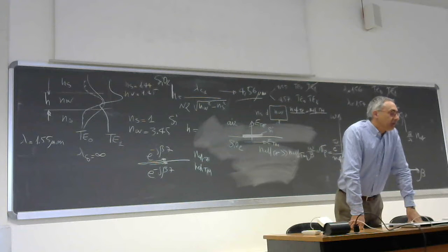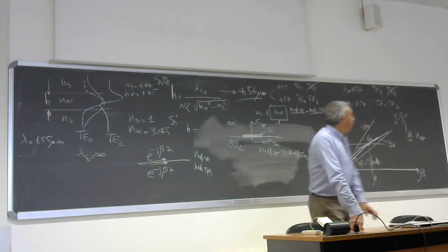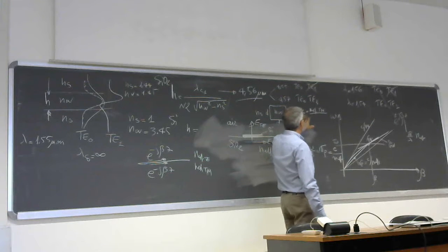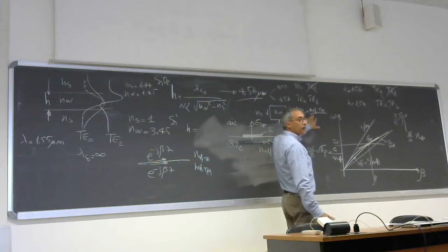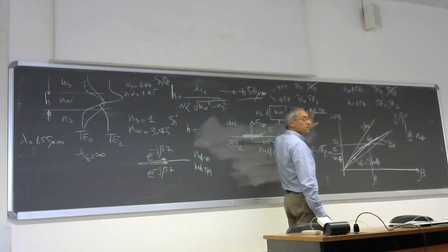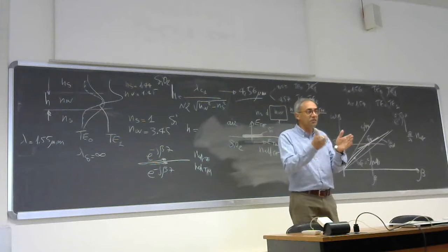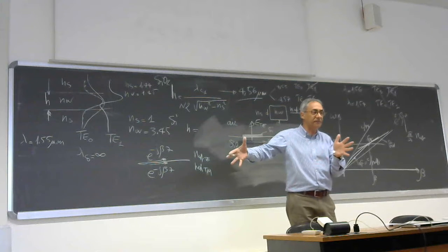There are two techniques to obtain a polarization independent device. We will see them during the course. One possibility is to really work on the technology of the waveguide and achieve this equality, so having two identical effective indices. Identical, from an engineering point of view, means that the first digits are similar, but at some point they are different.